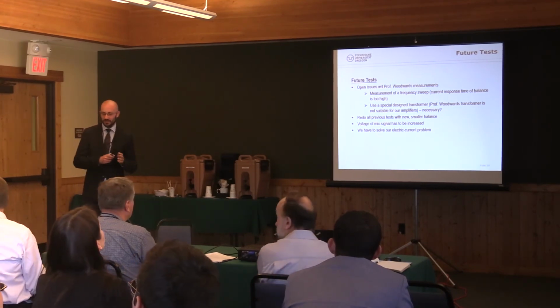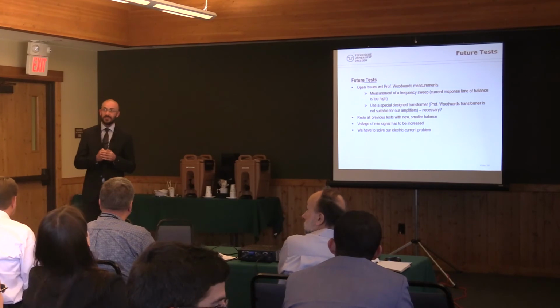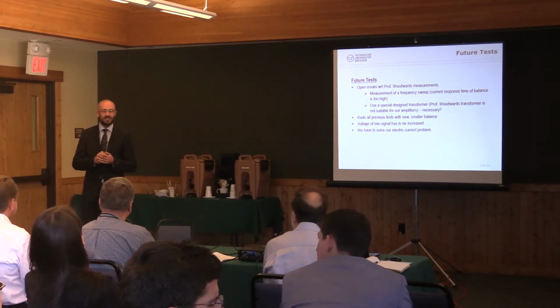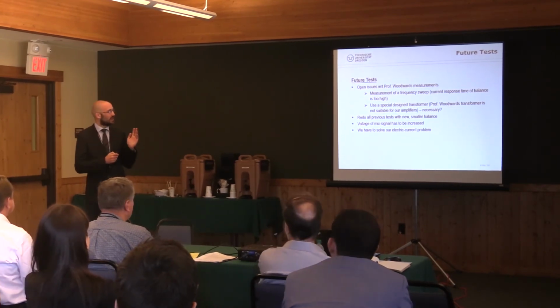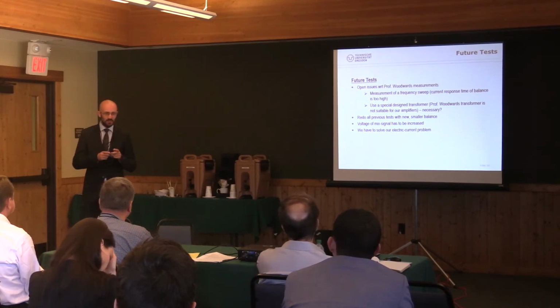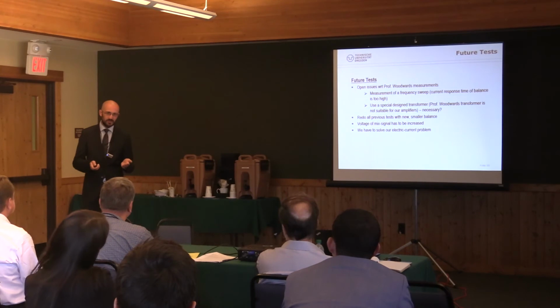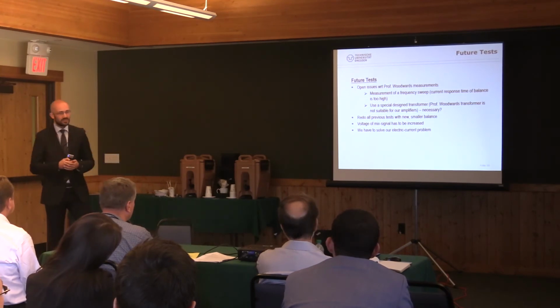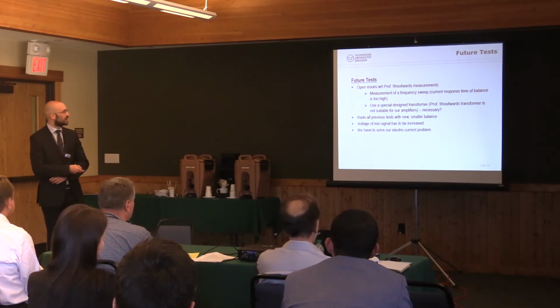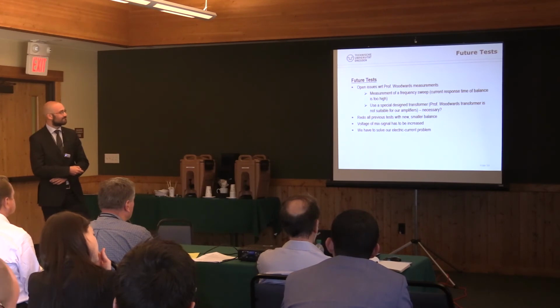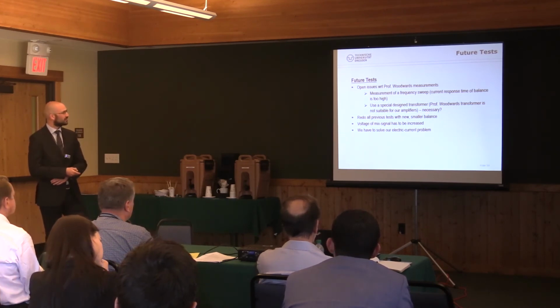Because the only transformers we have from Professor Woodward, and that's the reason we thought we never got any, we can't actually use with our amplifier, because the input impedance of the transformer is so low that the voltage would not be there. The current is not enough from our amplifiers. But like Maxime said, is it really necessary?